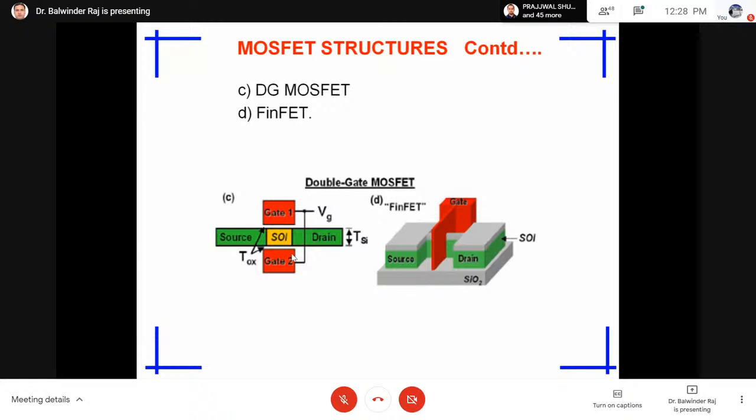So from here we can conclude, if I increase the VTH, my on current will reduce, and if we reduce the VTH, my on current increases. Okay, so with this trade-off, because I want to improve both speed and power, I require an asymmetrical structure. So I can say if I have 1 nanometer oxide thickness here, I can improve my speed. With high oxide thickness here, I can reduce my leakage current. So this is a structure where we can improve both speed and power.